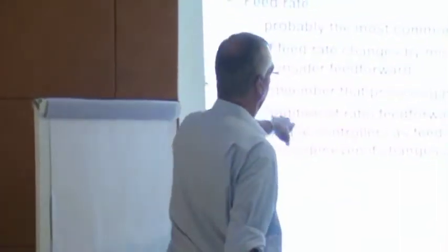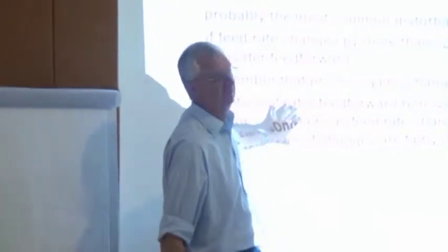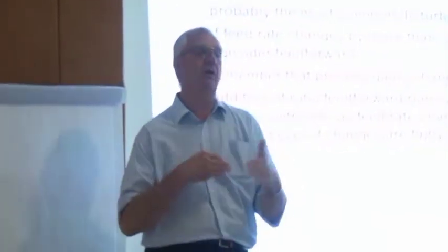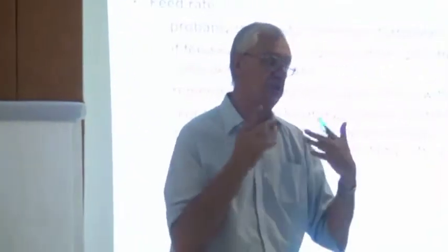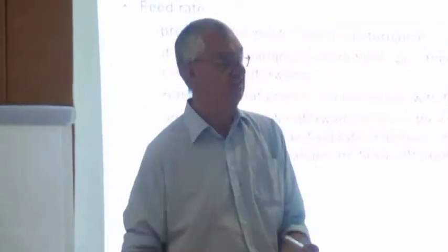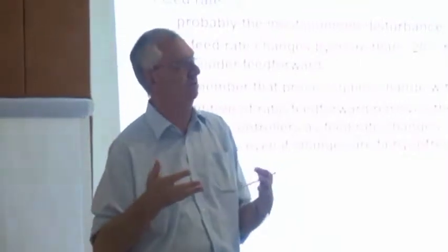And you remember, feed forward solves that problem. Ratio feed forward solves that problem of process gain varying with feed rate. So that's what we're going to do. We're going to do it for 2 reasons. One is disturbance rejection. Okay, if the feed rate changes, we'll change the reflux and the reboil at the right time rather than wait for the feedback controllers to do it. And secondly, it gives us a controller tuning advantage. We don't have to retune our controllers when we change feed rate.